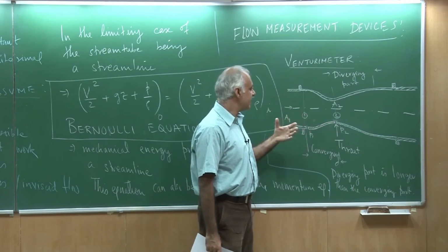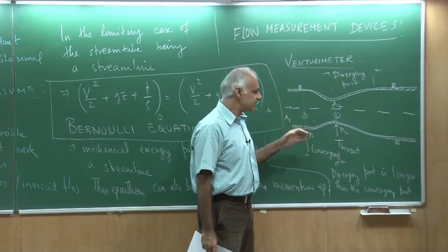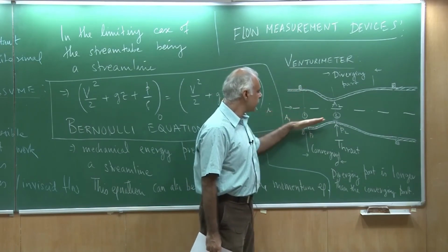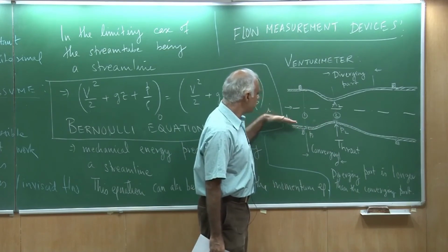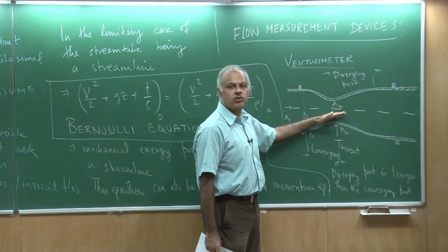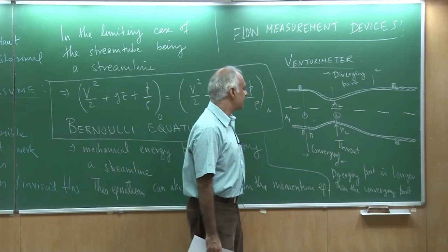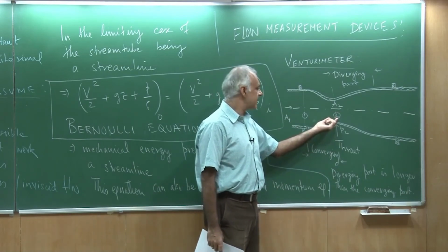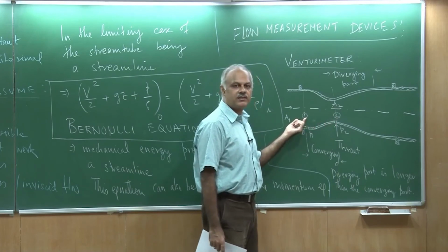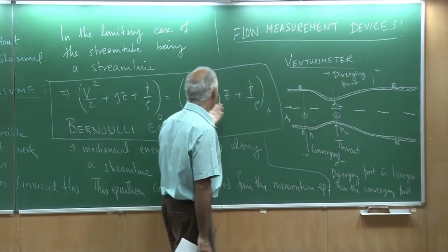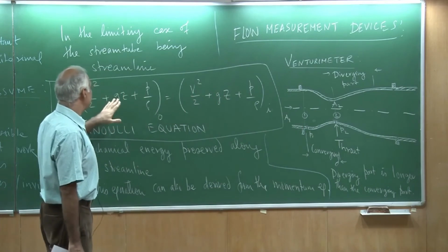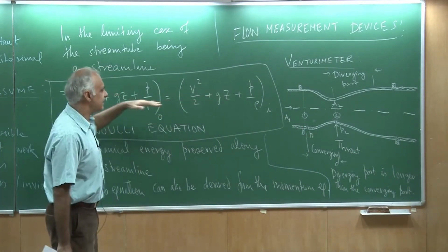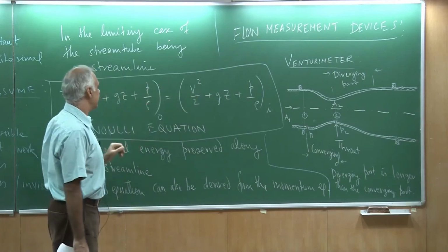Again, accelerate not in an unsteady sense, but as a fluid particle moves from the constant area section towards the throat, it goes through a convective acceleration. So the speed of the flow is larger at section 2 compared to section 1. And from the Bernoulli equation, I do not have the gz term because they are at the same level, so I can ignore it.